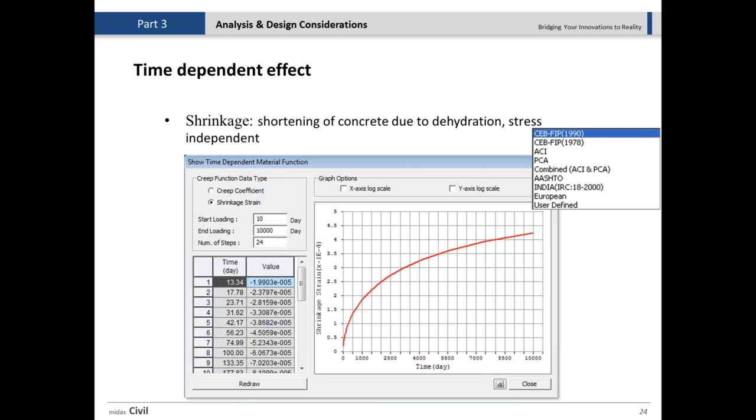So, coming back to the basics of post-tensioning and pre-stressing, what is important for us is that we are providing additional pre-stressing or post-tensioning forces in a way to give, let's say, a negative camber upward. Then it helps the structure to carry more load.